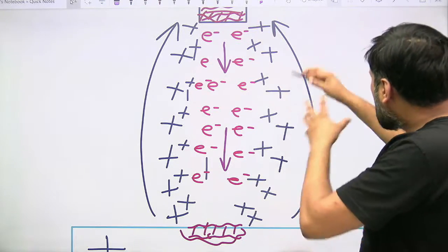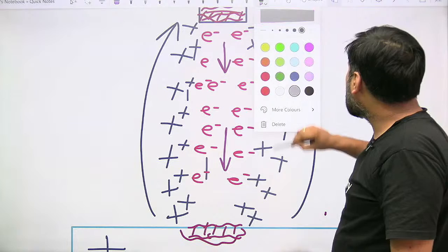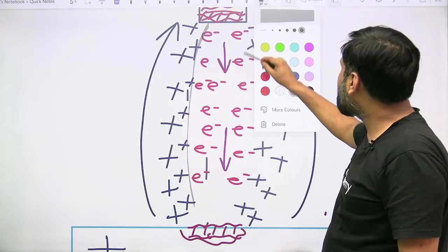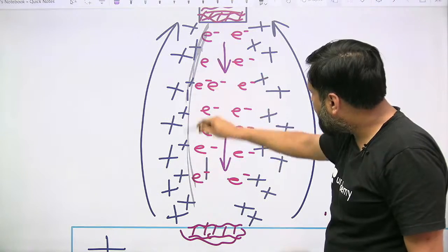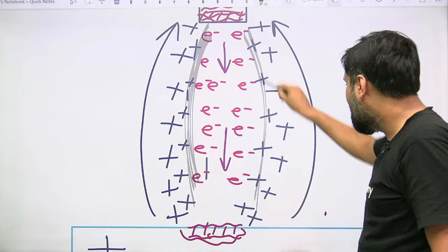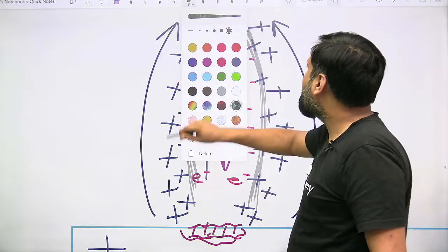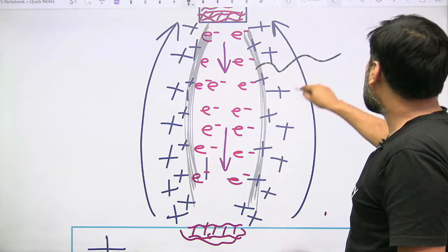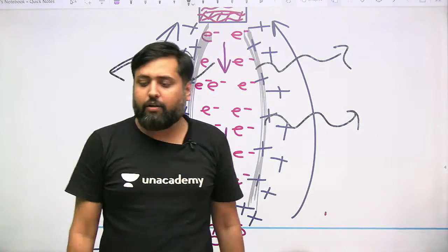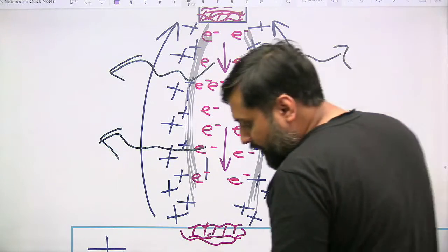So what happens is, those electrons and ions, my dear lovely students, which you find at the interface, collide with each other. And due to this collision, what happens? You see that, oh my God, ultraviolet radiations come out. And because of these ultraviolet radiations, you have to wear specs for welding, otherwise your retina will burn, my dear students.